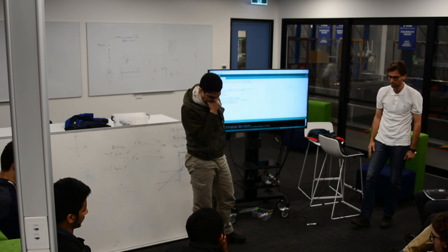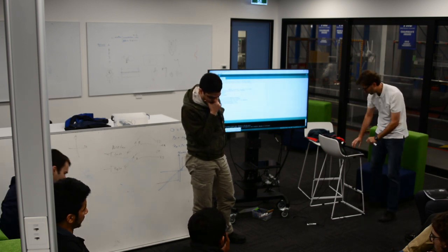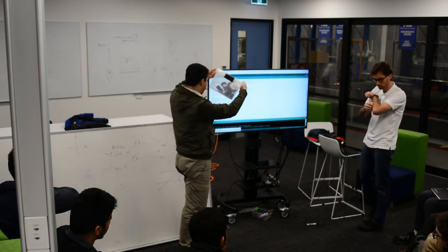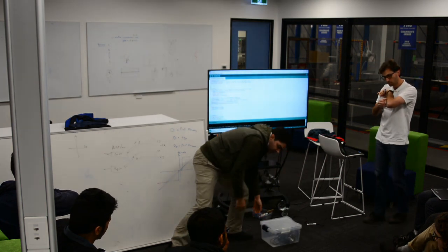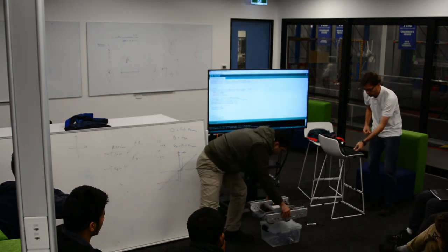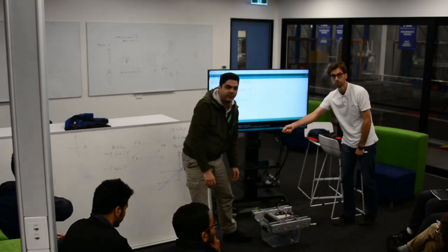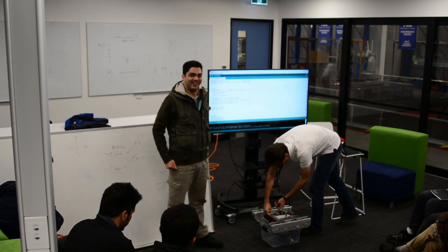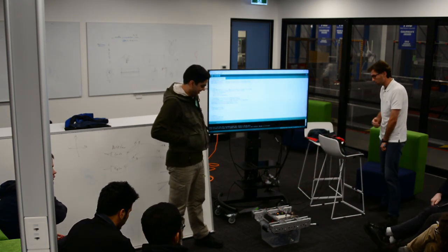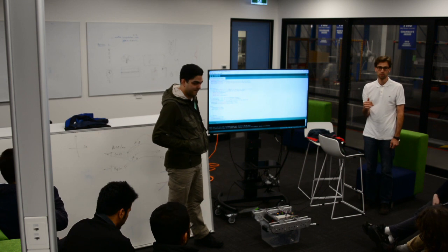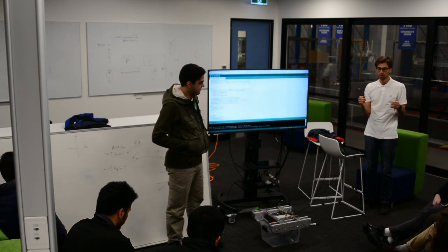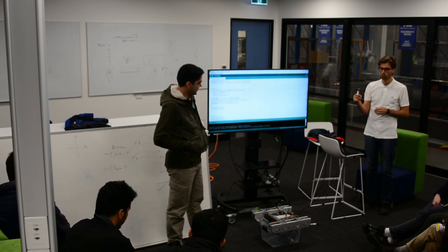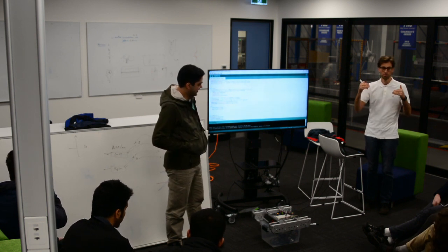You have a bunch of code at the beginning to self-calibrate the differences between motors. You could, I suppose, once it's fully assembled, potentially. I think the idea is, what you want to do is have a tight position control system on each side and just keep it in position all the time. So you don't want to send your proportional controller a huge move. You want to send it a bunch of small moves. Move 10, move 10, move 10, move 10, move 10. Then they'll both move at the same speed. That's essentially speed control.